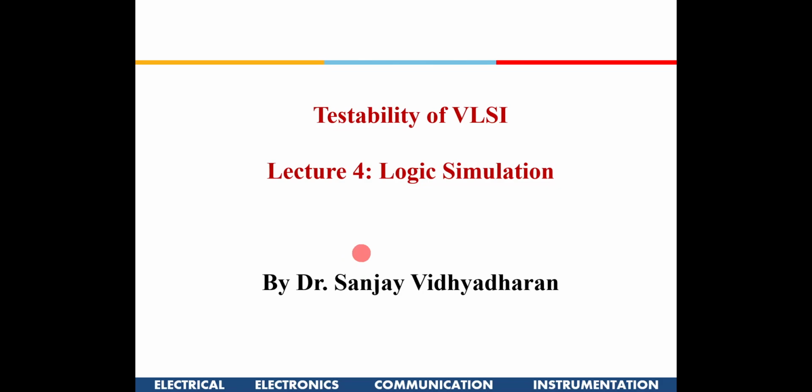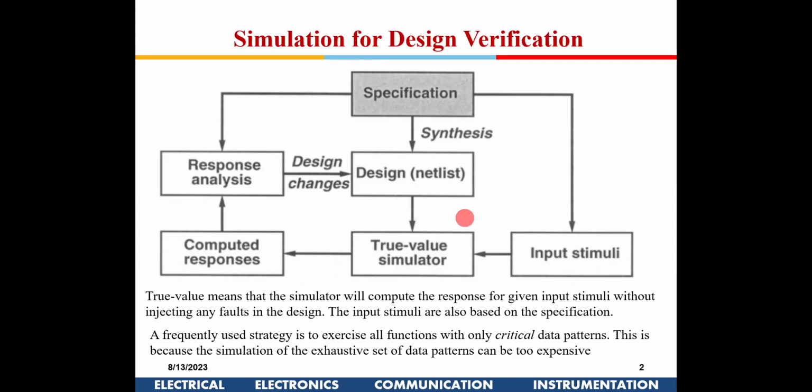So today, before that itself, we need to do the logic simulation before fabrication, because this data is also important for our testing, right? So what is logic simulation? Once we have a specification of the system, and the design is synthesized, you have a netlist, right? And from the specification itself we know, okay, for these kinds of inputs, these are the expected outputs, so that is available.